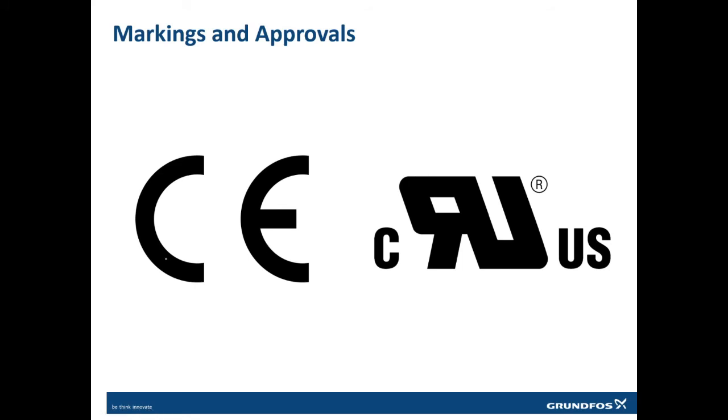Approvals and markings. Once you receive a motor, if it has a CE mark, that means this is applicable to all IEC 60034 standards. Or if you have a CURUS mark, that means it is a NEMA motor, complying to NEMA standards. Now coming to the last topic of today, which is motor protection.